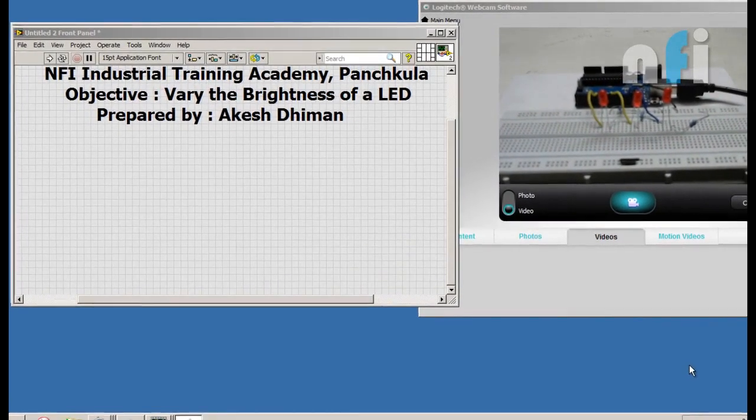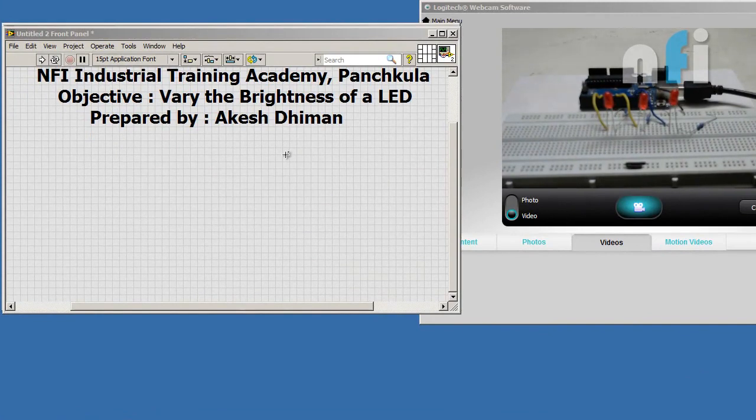Hello everyone, welcome to our next exercise in which we will control the brightness of an LED. To vary the brightness of the LED you'll need PWM pins, and Arduino Uno provides you 6 PWM pins. I have connected my LEDs to pin number 6, which is a PWM pin, to pin number 9, which is also a PWM pin, and to pin number 12, which is not a PWM pin.